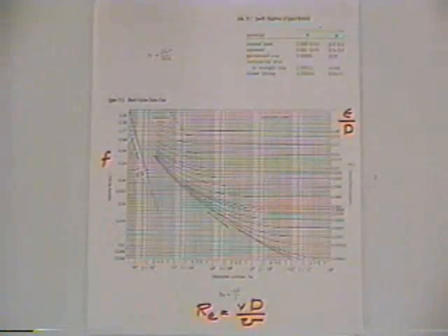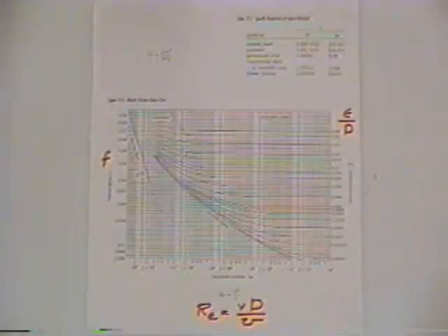And there's different areas of the Moody diagram. And so another concept in fluid mechanics, which comes into play here, which we mentioned very briefly in another application, is the concept of laminar versus turbulent flow. And again, laminar flow is where you've got smooth layers of flow, just smoothly flowing one layer over the other. Turbulent flow is random motions, as the fluid particles are going this way and that way in a random fluid flow field.